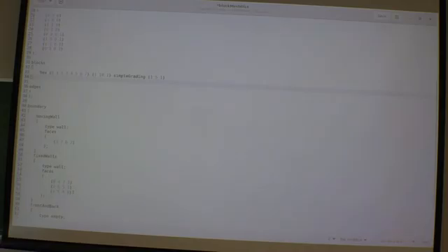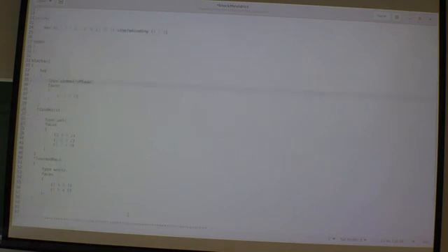Then the top wall, that's not a moving wall anymore. What should we call it? Well, top. Why not? It is of type symmetry plane. Oops, like that. And then I have the bottom. And it's of type wall.